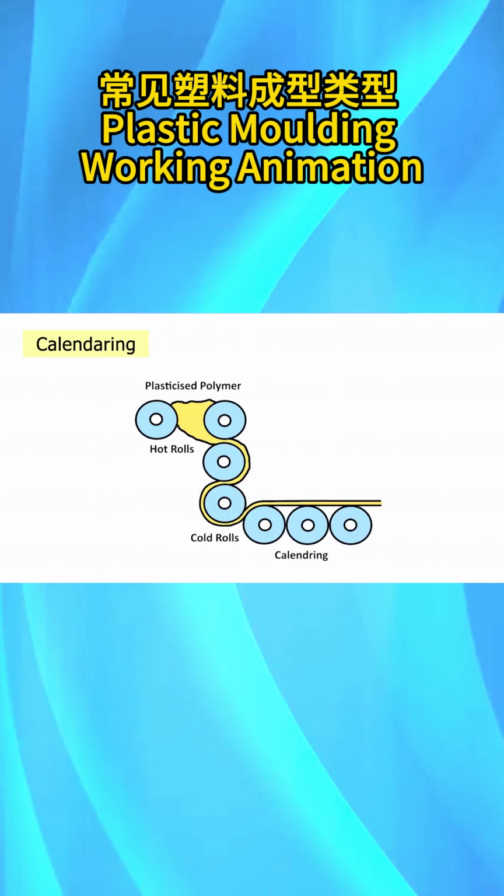In calendering process, the melted polymer is subjected to heat and pressure in extruder and formed into sheet or film by calendering rolls. The temperature and speed of rolls influence the properties of film. Here calender is a series of hard pressure rollers used to finish or smooth a sheet of material such as plastic.